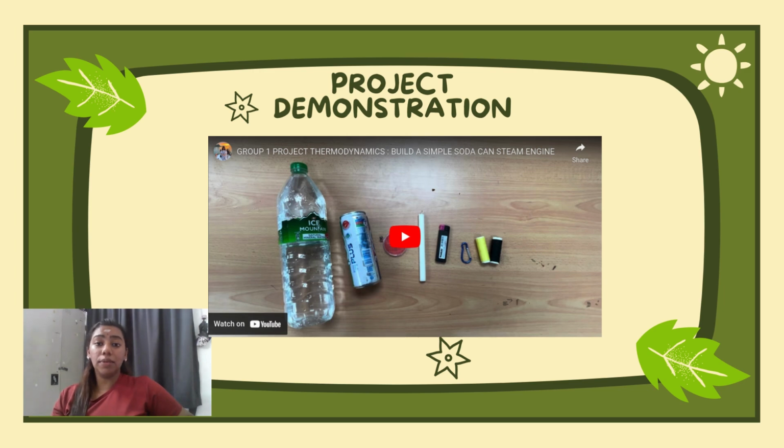Next, we would like to present our demonstration video. Here's footage from our soda can steam engine demonstration. We can observe the water turning to steam as heat is added, increasing the internal energy according to the first law. The high pressure steam is then expelled through angled holes, generating rotational kinetic energy. However, as entropy increases, the rotation eventually stops when no more steam is available to power it, illustrating the second law.